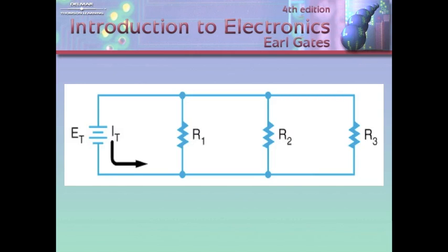Our next slide shows us a graphical depiction, a schematic of a parallel circuit. One of the things that I want to focus your attention on are these little dots right here underneath R1, R2. What are these called? Junctions or nodes. And this is where business happens, right? This is where current is going to divide. This is a very important troubleshooting tool, again, for technicians.